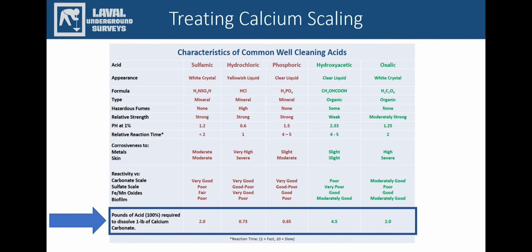It should be noted that the organic acids are not very good at dissolving calcium carbonate. Though oxalic acid has a low pH, when dissolved in high calcium carbonate supplies, it can form calcium oxalate. The best way to avoid a scenario like this is to test your well properly and to use a scale inhibitor as well as an iron bacteria reducer.